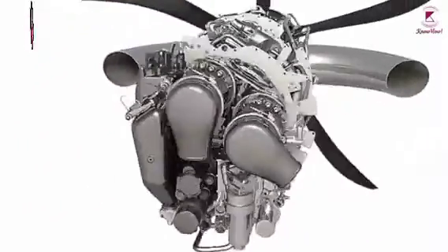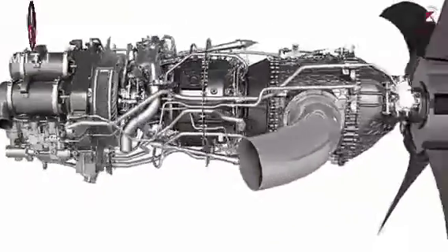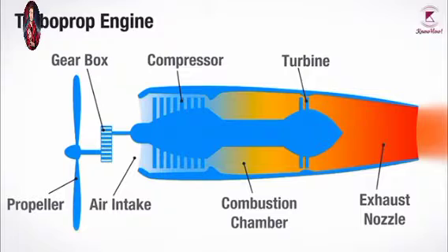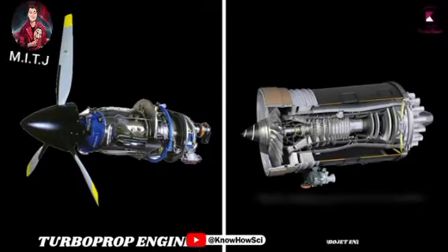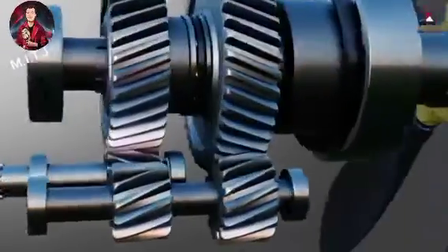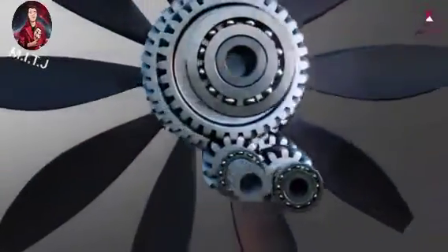A turboprop engine uses the same principles as a turbojet to produce energy. That is, it incorporates a compressor, combustor, and turbine within the gas generator of the engine. The primary difference between the turboprop and the turbojet is that additional turbines, a power shaft, and a reduction gearbox have been incorporated into the design to drive the propeller.